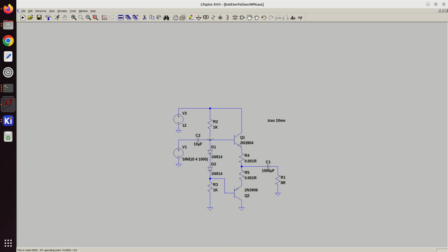So this will be 6 volts plus 0.7. So this will just barely turn on this transistor. This guy will be 6 volts minus 0.7, and this is 6 volts, so that's going to barely turn on this transistor. So because 2 transistors are turned on, when we apply positive to it, then this guy should just continue to conduct, but conduct more. And when we apply negative, this should continue to conduct, but conduct more in the opposite side.